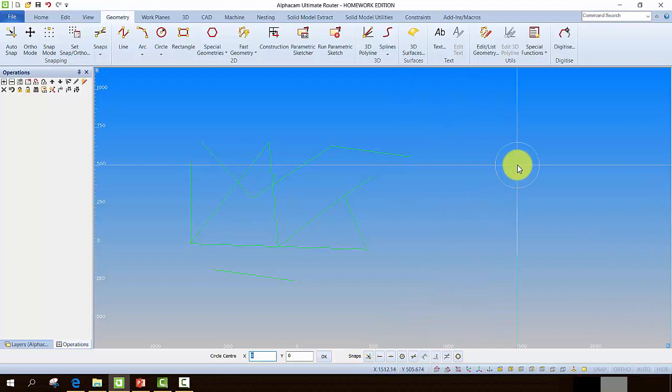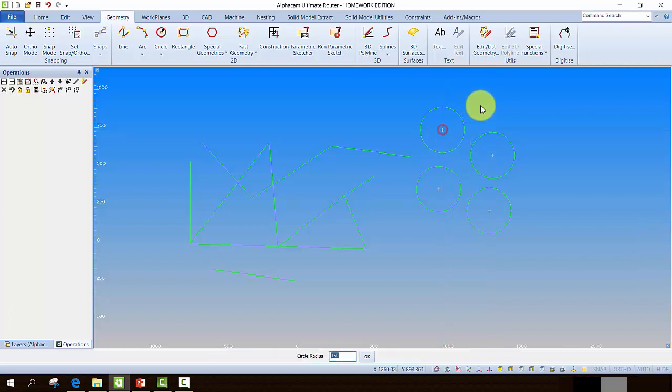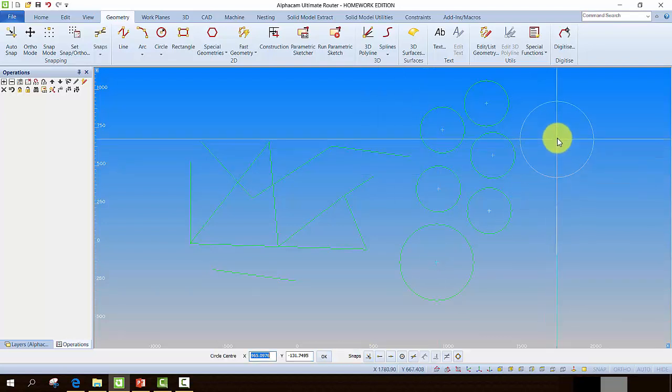And in that case, it creates the circle with that radius, and now it prompts you for the insertion point. So I'm going to click and position it right there. And you'll notice the command is still active. It still has the circle command active. It's preloaded it already with the circle radius of 150. So I'll just press OK again and drop in another. Or press enter and drop in another. So pressing enter very quickly allows you to drop in a number of those circles. For instance, if I now want a 250 radius circle, press enter, I can drop that in as well.